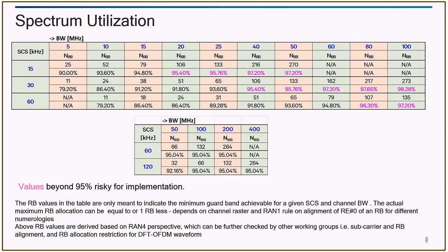What I'm trying to say is, when I come back next time, maybe it won't come in this location. It can come in this location, here, and then further over here. So there is a mathematical equation which specifies where you are going to find it. This is known as an SS block. So PSS, SSS, and PBCH all in one package, in one single box would be transmitted,